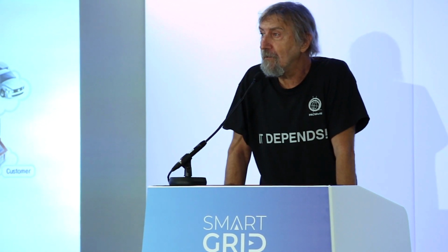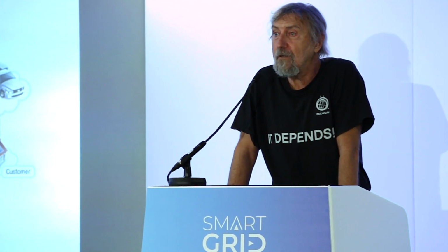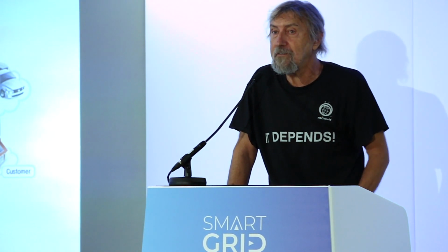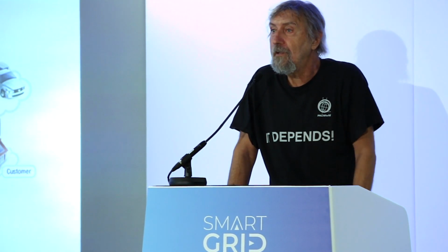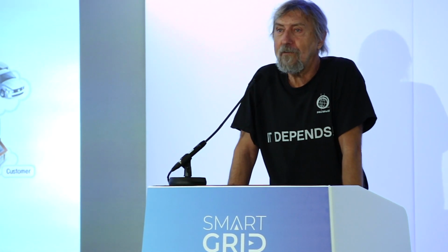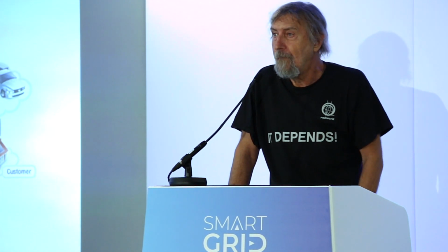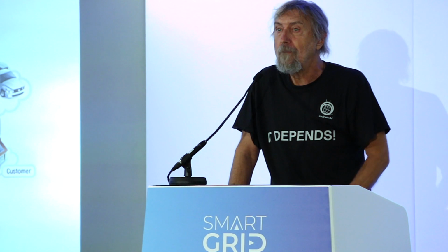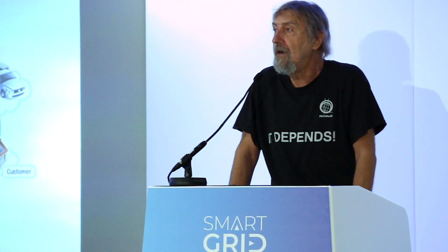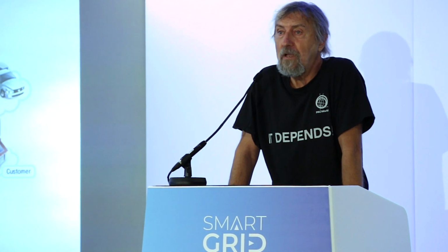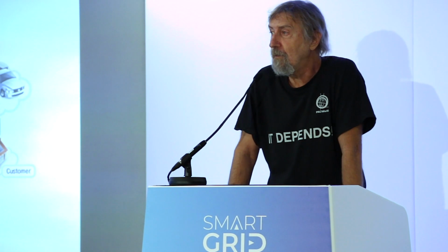Today, some people in the protection industry complain that we don't have enough fault current. And there are some crazy people that say we have to program the inverter controllers to produce fault current, which I find absolutely ridiculous. We have to find new methods for detecting the faults and then taking care of the abnormal condition in order to maintain the stability of the electric power grid and the power quality that we provide